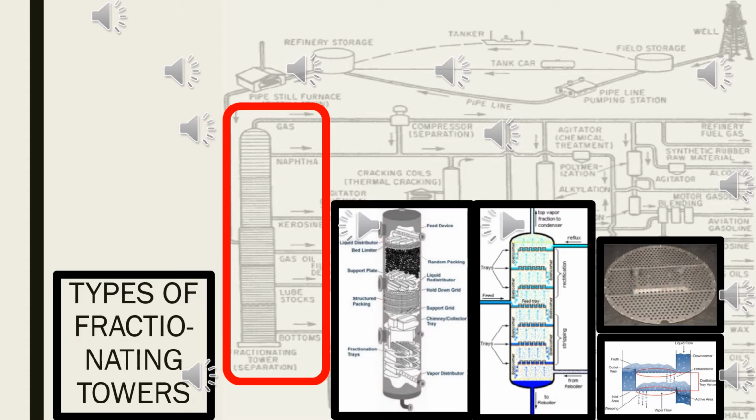One type of tray you could consider using is sieve trays, and these are simply metal plates with holes in them. Vapor passes straight upward through the liquid on the plate. The arrangement, number, and size of the holes are design parameters that you can manipulate.